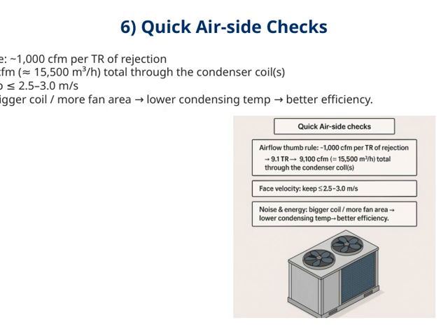Next, I want to emphasize face velocity. Keeping this at or below 2.5 to 3 meters per second is crucial. Why? Because it helps maintain efficient heat transfer and prevents issues like airflow noise or pressure drops.